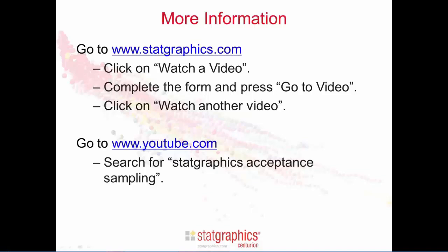Second question, why do you mention the military standard? It has been officially retired and is now obsolete. Z1.4 and Z1.9 are the substitutes. The sample sizes are exactly the same, whether they be military standards or the ANSI standards.